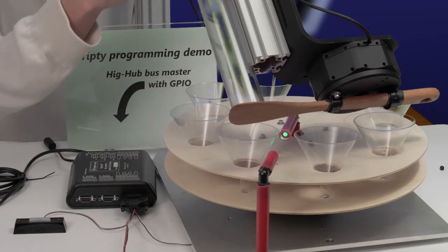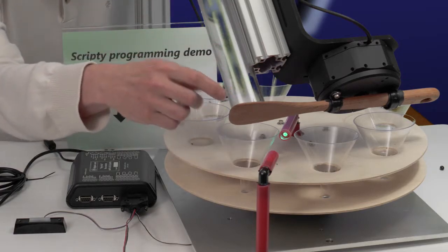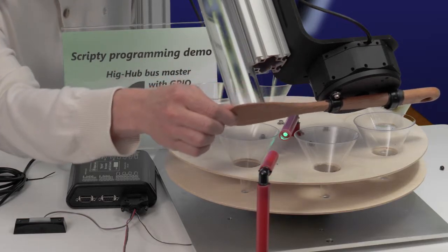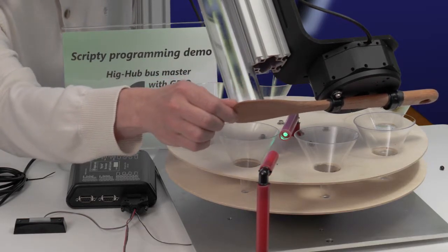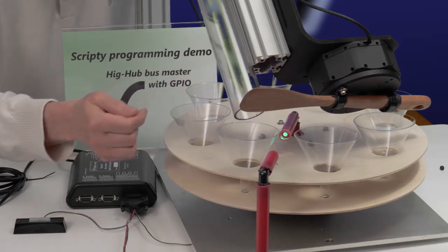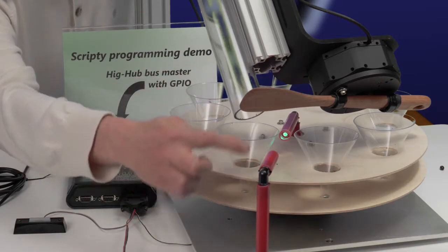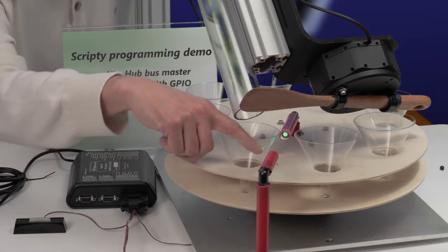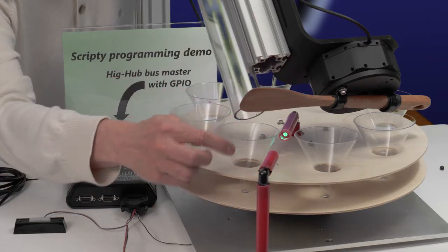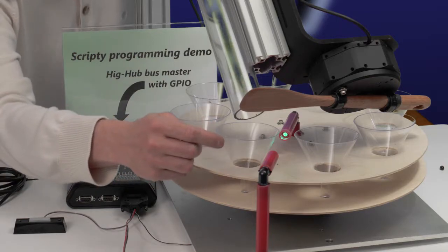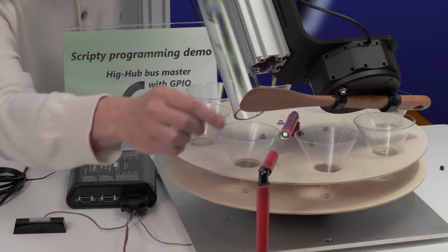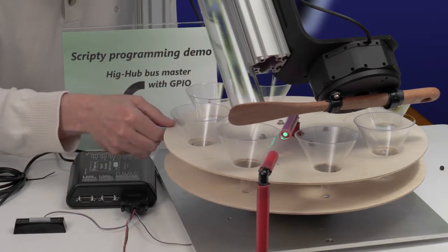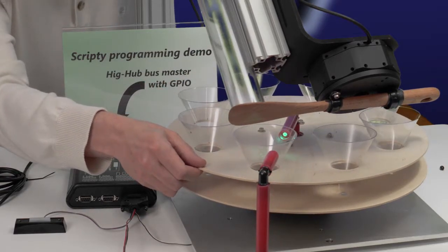We will load the coffee beans into this clear tube, where we have a second Hig Mover actuator operating this spatula as the gate control for the flow of beans into the cup. We also have a photoelectric eye, this green light here, which will detect the level of the beans in the cup. When they rise to a certain level, that will cause the photoelectric eye to trigger the closure of the gate, whereupon the carousel will advance to the next cup.